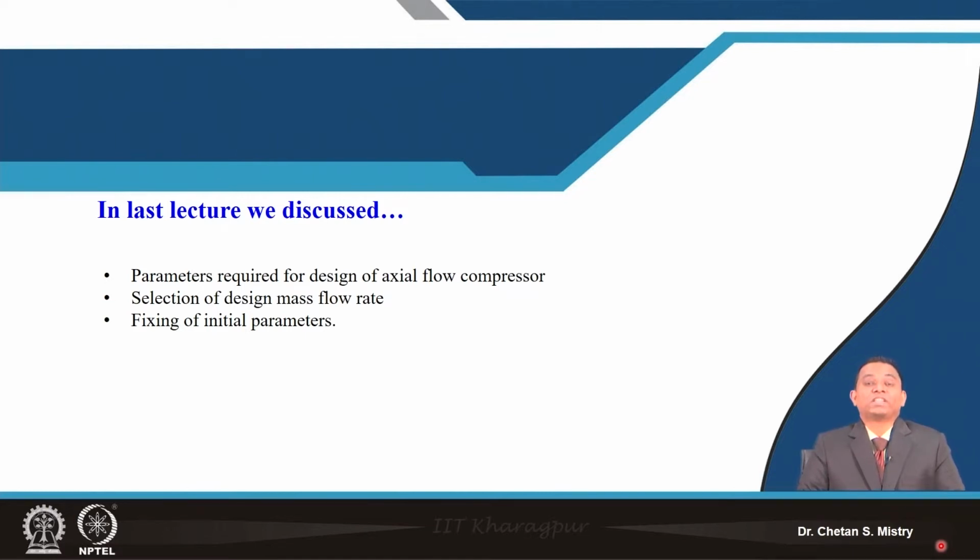For later stages, the blades are shorter, which gives flow three-dimensionality, leading to increased losses and reduced efficiency, and our expected pressure ratio for such blades is on the lower side. We also discussed that for supersonic engine design for military applications, the middle stages may also go transonic, because there we have no concern about fuel economy. Now with this background, let's move ahead.